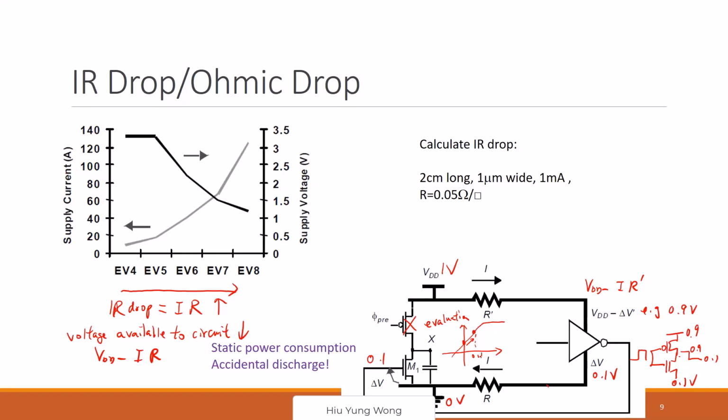So you can have maybe how much? If the subthreshold slope is 60 millivolt per decade, this one costs more than maybe 16 times. Not 16 times. It's almost turning off, right? Sorry, I'm wrong. It's about at least 10 times more leakage current, right?